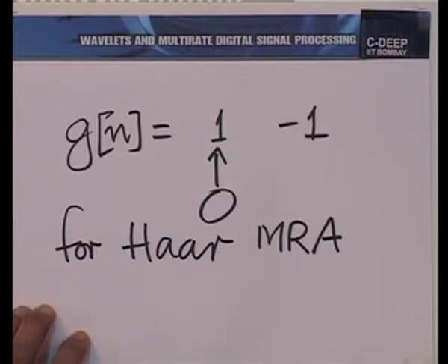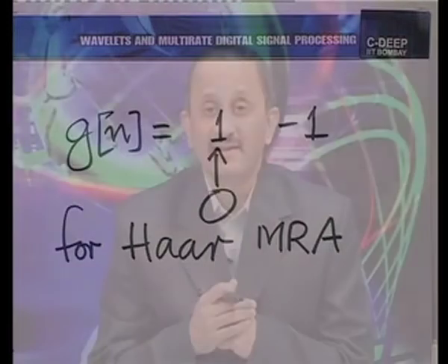And in fact, we said that what these equations told us was something much deeper than the containment of phi(t) and psi(t) in V1. In a sense, these equations tell us how to go from the filter bank to the wavelet and from the filter bank to the scaling function. We had just hinted at this in the previous lecture, but now we make that idea very, very concrete. So, let us begin by looking at the Fourier domain. As I said last time, we need to take the Fourier transform, because that is where we shall see something very interesting.